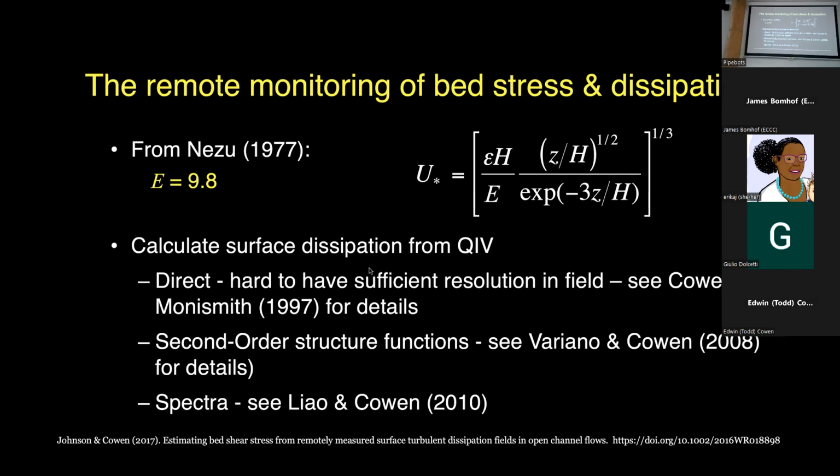And so you can get at surface turbulence lots of ways from surface dissipation. In the lab, we've historically done it directly, and direct measurements really go about resolving the fluctuating strain rate tensor. But to resolve surface dissipation directly, you need to be down at order the Kolmogorov length scale of the turbulence, maybe at 10 times that. So you're talking millimeter scale, maybe getting up to centimeter scale in weakly turbulent flows.